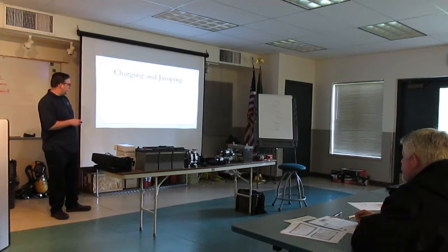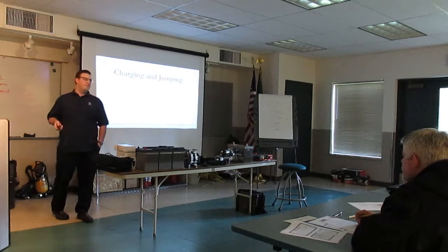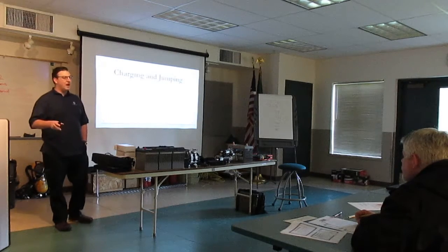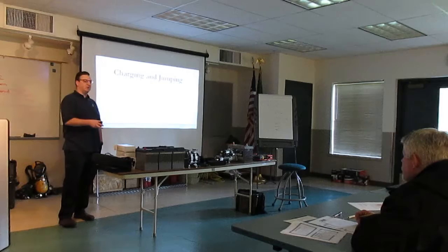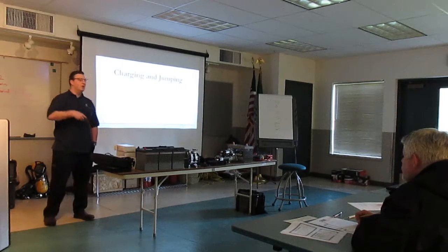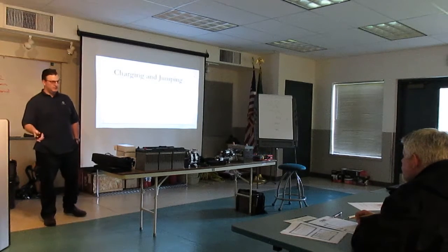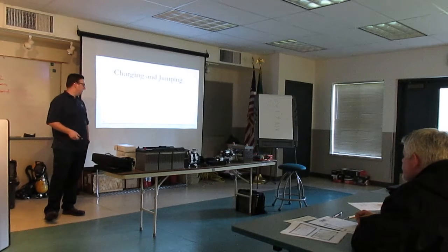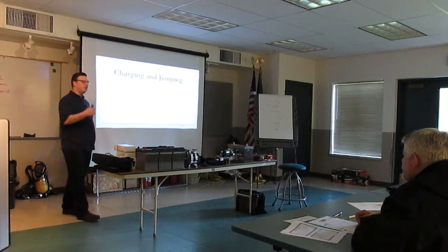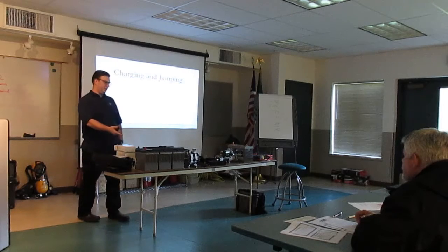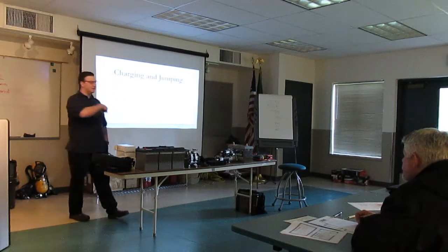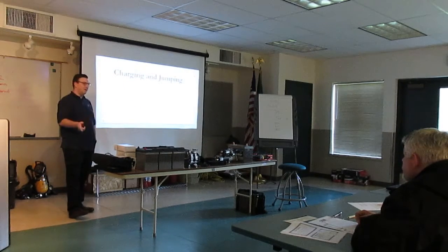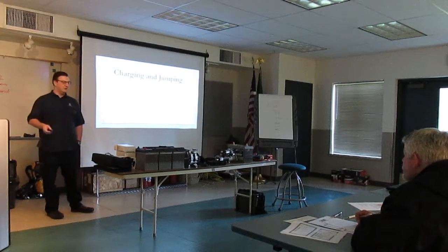Your charging rates and settings are going to vary by your battery type again. So what batteries you have, you've got to make sure how they're supposed to be treated, how they're supposed to be taken care of. What do they want? What do they need? And what are you dealing with? So when you just come up to a vehicle, what voltages are you expecting to see on those batteries? Because again, it's going to be a little bit different. Same thing with the charging voltages. They're going to be a little bit different based on your battery types and what you're seeing.